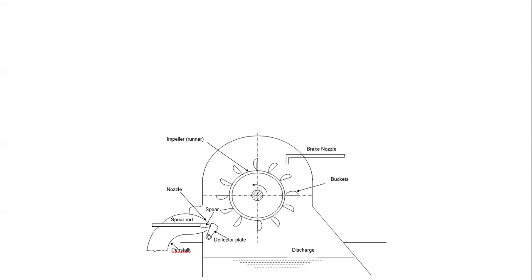In some cases, like in this Pelton wheel, water could be falling from a particular height. Then it's directed to the various buckets. Inside the buckets, you have the vanes which are splitting the water. Then when the water is redirected through some angle, it will have some resultant force. This force is then transmitted to the impeller, which is connected to the generator, and then you have electricity being generated because the rotation is now available.